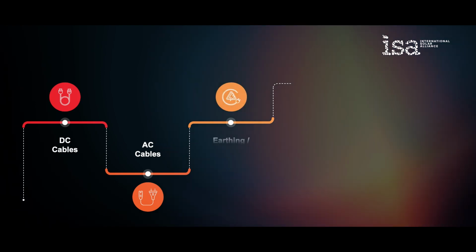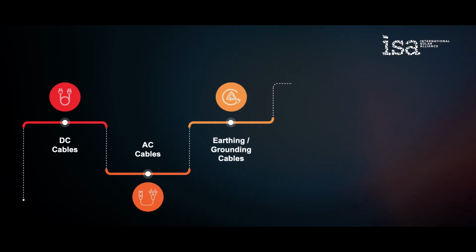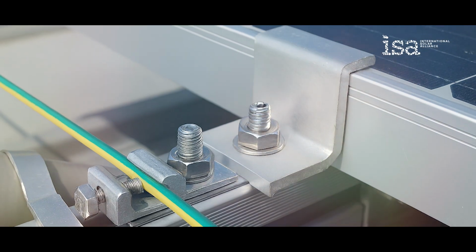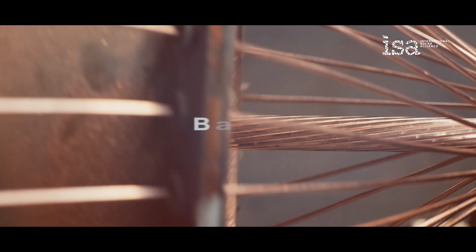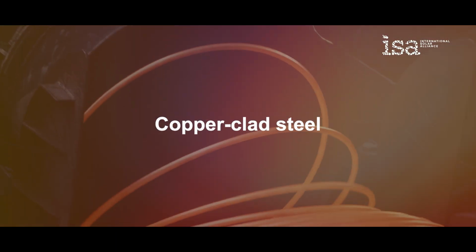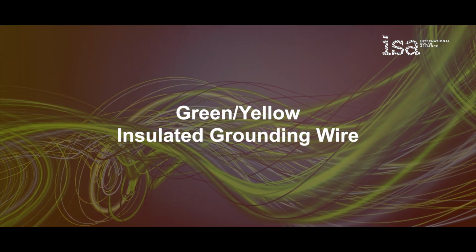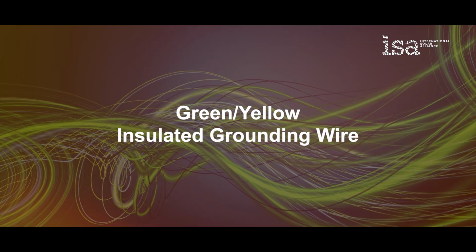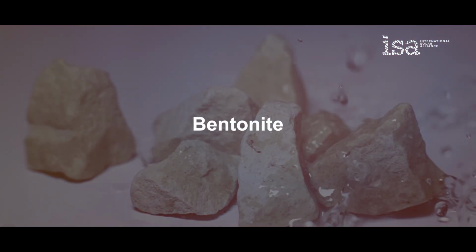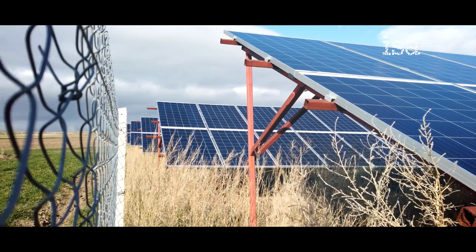Earthing cables are critical for protecting equipment and personnel. They create a low-resistance path for fault currents and lightning discharge. Materials commonly used include bare copper, GI strips, copper-clad steel, green/yellow insulated grounding wire. Chemical earthing, using compounds such as bentonite, is widely used to achieve stable, low resistance.